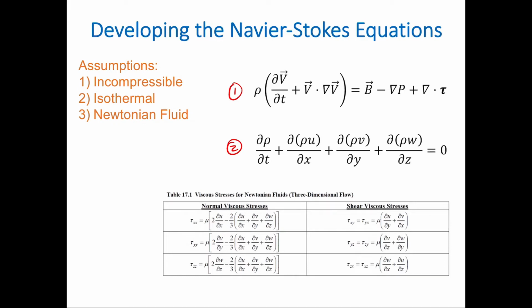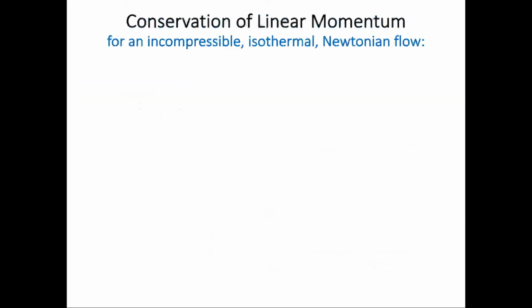These assumptions here are both shear stress that you've seen, but it also throws in a little bit of mix of some basically hypotheses from Stokes, and the appendices in your text can also help you walk through this. So then let's say this is equation 3, even though it's a variety of equations. If we take these equations, basically 2 and 3, and we put them into 1, and we throw in a dash of those assumptions that we just had there, we end up with the Navier-Stokes equations.